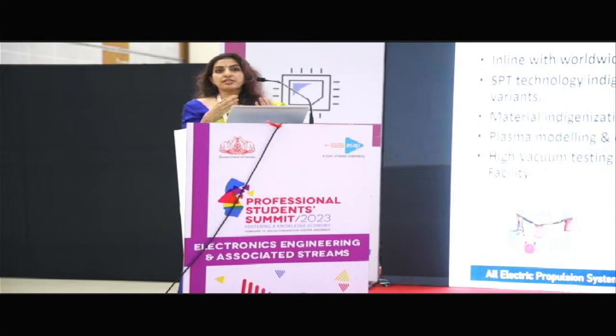That is nothing but the specific impulse, and that is roughly equivalent to the efficiency in our electronic packages. So the higher this number, the higher the efficiency of the fuel. So in electric propulsion, we use electric power, and that is more efficient than the chemical fuel. So we can see a figure like 2000 against 320 in chemical propulsion. So with less fuel, we can manage more payload. You can also see that a 5.5 ton class normal chemical propulsion satellite with, say, X amount of payload can be converted to a 3.5 ton class EPS satellite. So that is a major advantage of EPS.